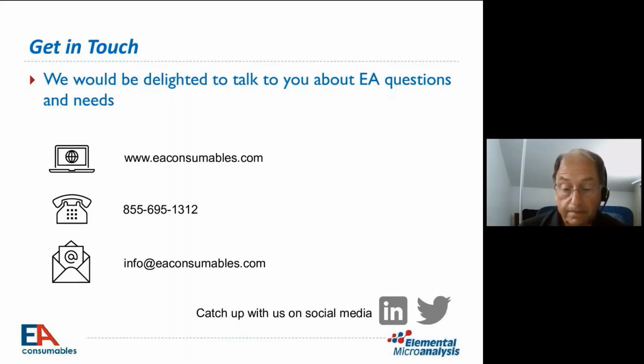Okay, great, thanks. This next question says, how will I know if my instrumentation needs maintenance or servicing? Sometimes it's very obvious. For example, when the reduction reagent is used up, all of the added oxygen for the combustion will not get scrubbed out of the system, and it will go to the detector and look like nitrogen, and your nitrogen peak will be humongous. So that's really obvious. All of a sudden you have a 5% nitrogen, and the next sample you have 2,000% nitrogen or something like that.